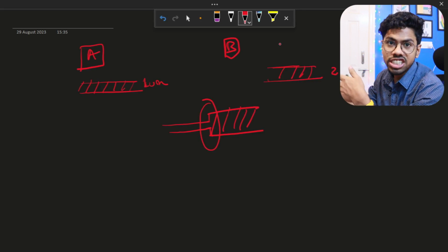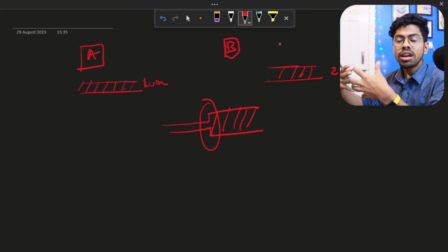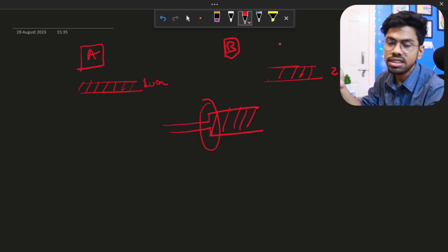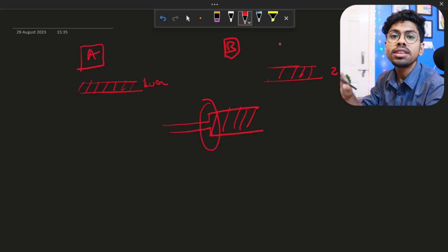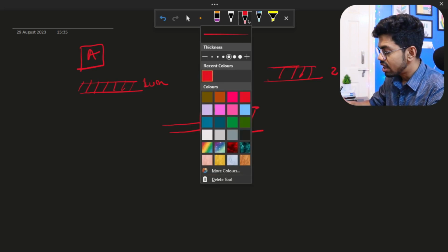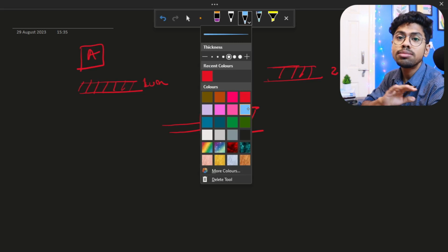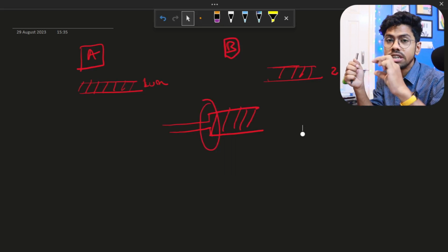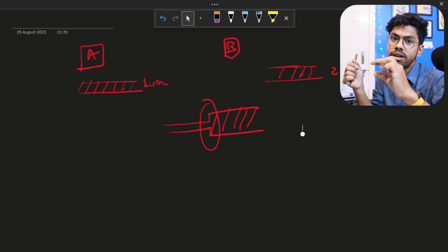So there would be an integration engineer who is going to integrate both blocks, and he or she will have a lot of work to do to clean those DRC errors. So why create those DRC errors in the first place? Therefore, everywhere we first decide some standard guides, and those guides help us determine the width of our metal.